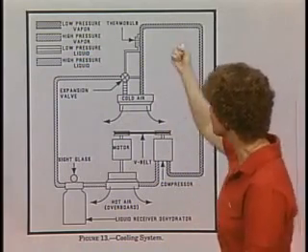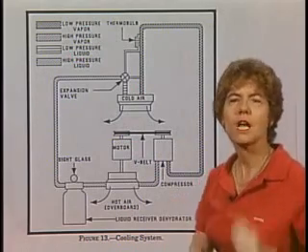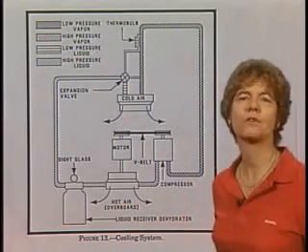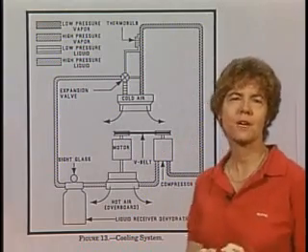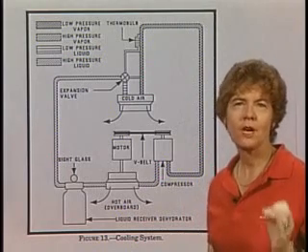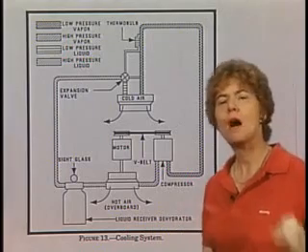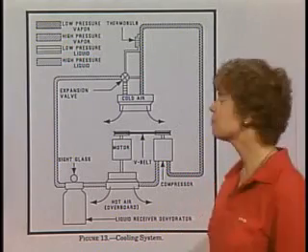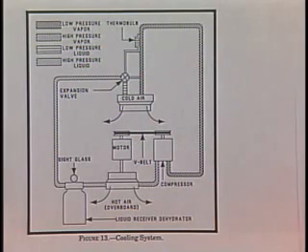That vacuum pump lowers the pressure, and by lowering the pressure, it lowers the boiling point of the water, turns the water into vapor, and then can draw out the vapor. So what you need to know for the test is that the evacuation of a vapor cycle cooling system, the way it does it is by lowering the boiling point of the water and drawing out the vapor.